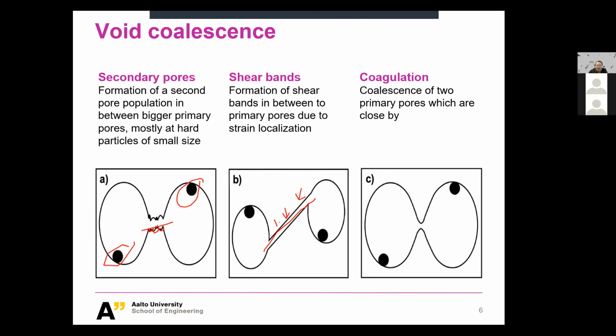If your dislocations are like this, edge dislocations, they just go towards this kind of stress concentration area, and you will develop this kind of shear band when you have too many dislocations. Meaning that point will become vulnerable, and finally that leads to a failure. So these two voids are going to connect to each other.